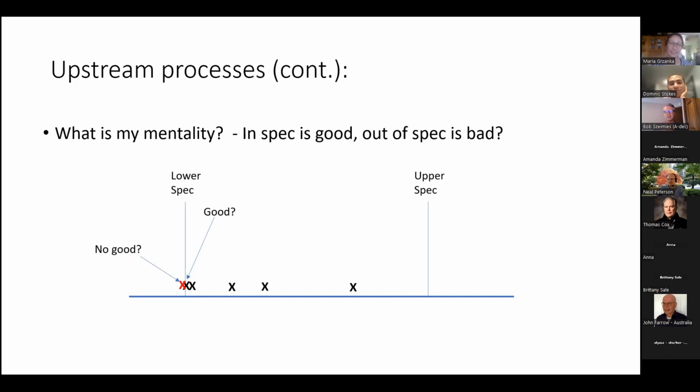But that's another story. So assuming we have an incredible gauge, that baby is right there. But by golly, it's in, so it is good, right? Now, what about the red X? What about that part? It's a tiny bit away from the other one, and we're saying, oh, that one's no good. Absolutely not. That one's no good because the center is to the left of lower spec.